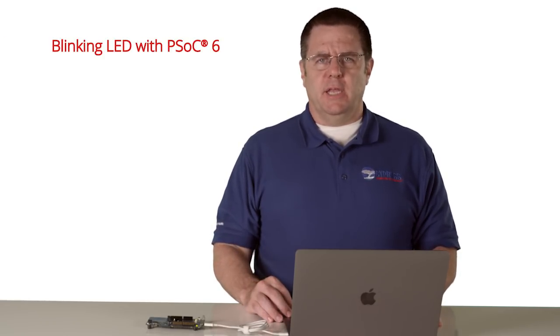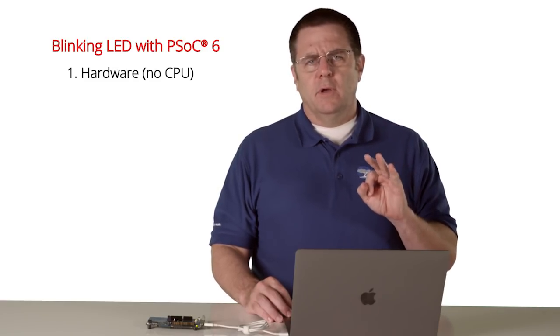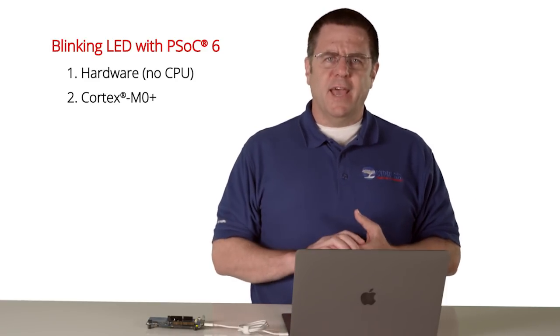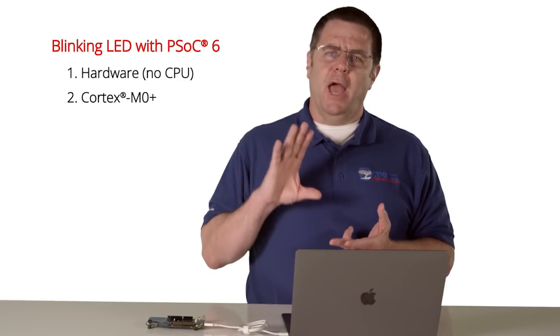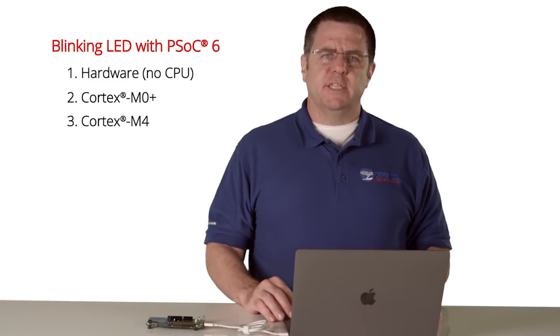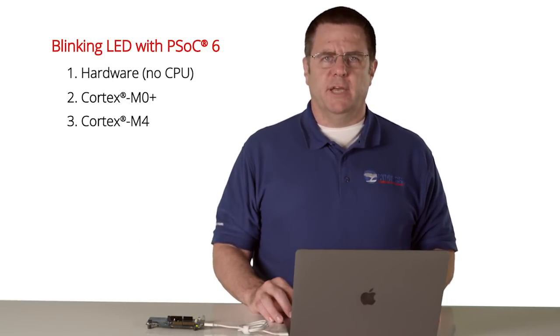For this example, we're just doing a blinking LED, so I'm going to show you how to blink it 3 different ways. First of all, just using the hardware in the chip, no CPU involvement. The second way, using the Cortex M0 Plus and building firmware that works on the M0 Plus. And finally, on the Cortex M4 and using firmware that runs inside of the Cortex M4.